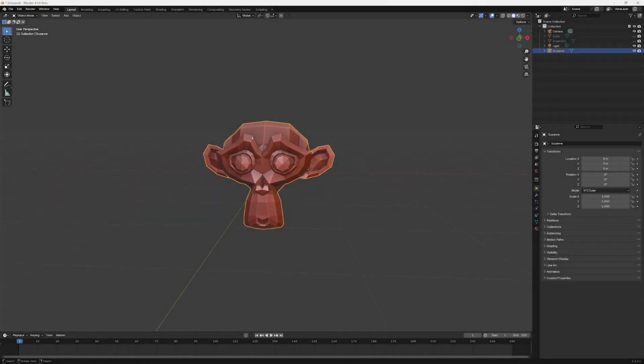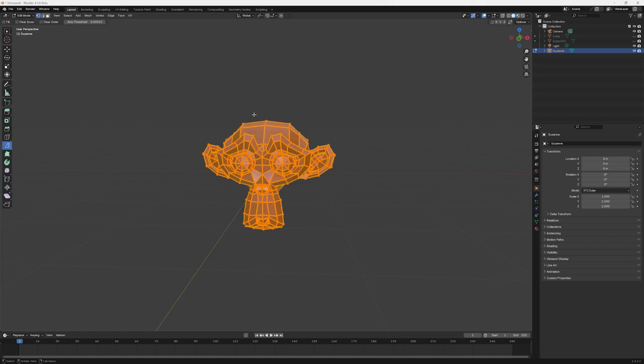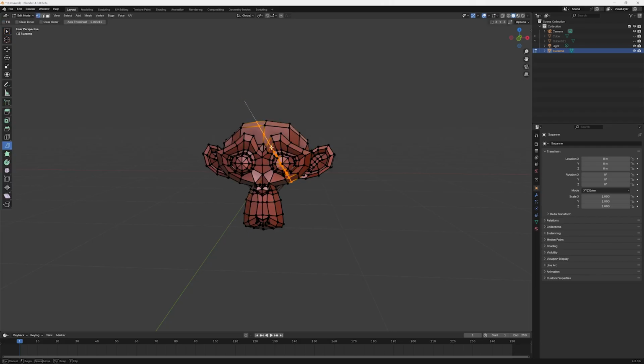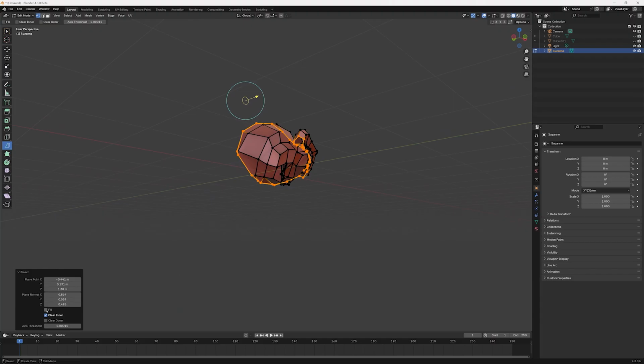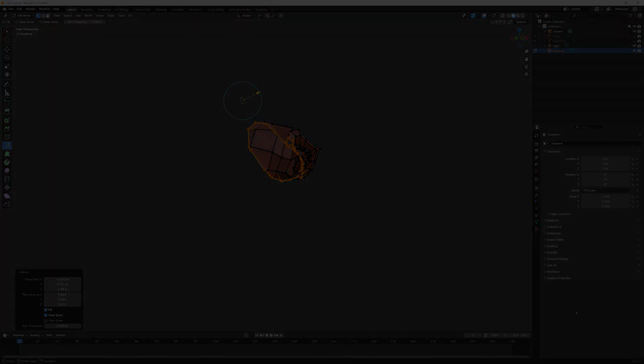One more point to note is that the fill option may not work as we cut through an object containing separate meshes that have been joined together. We can see this if we make a cut through a monkey head, where we are exposing elements from both the head and an eye. Selecting the fill has no effect.